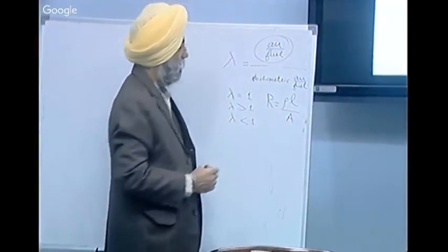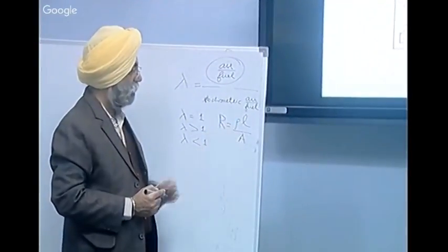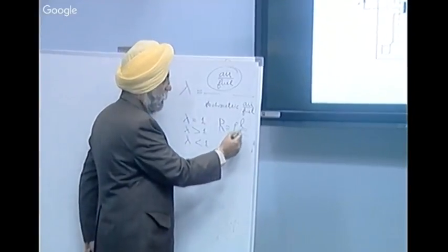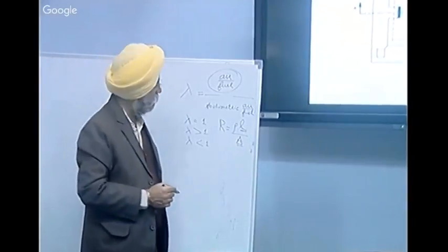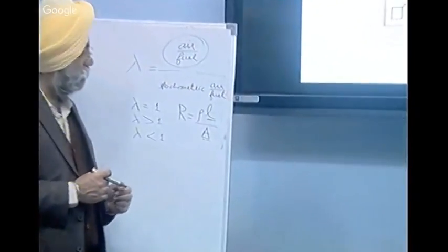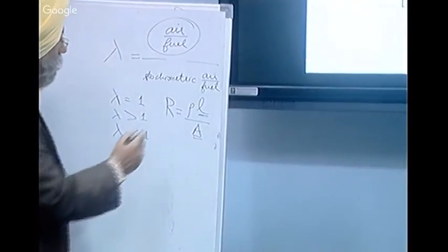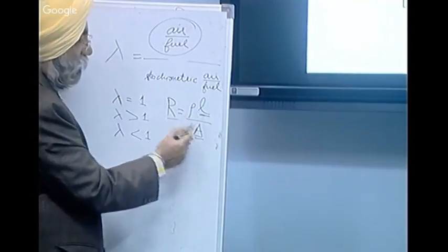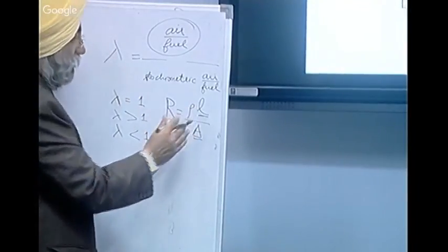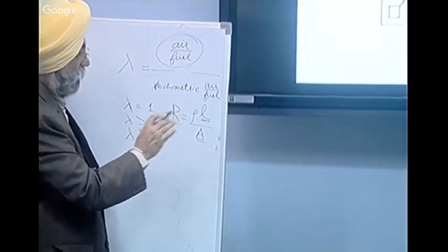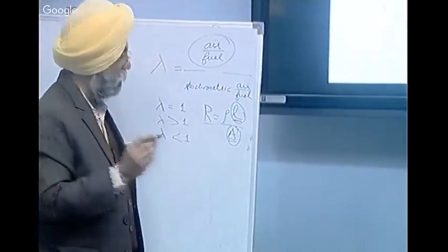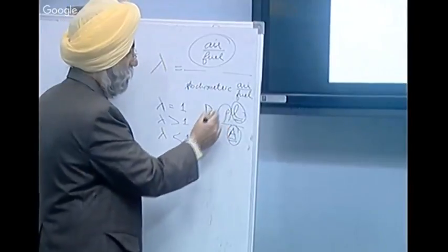So the resistance depends upon the type of material and its dimensions. In strain gauge type pressure sensors, the force is applied to the sensing elements and their dimensions change, so we are changing L and A. But in a piezoresistor, we are not changing the dimensions, we are changing the resistivity.